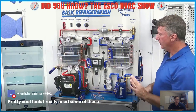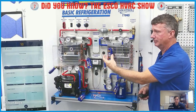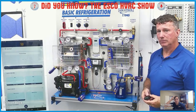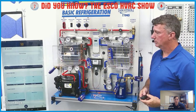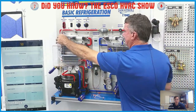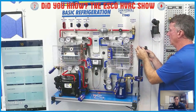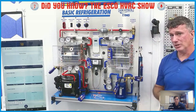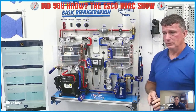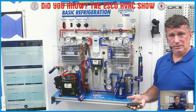Okay. So another item that you sent for us to be able to experiment with is? Yeah, the mano or the manometer, right? So we're taking our static pressures of the system or looking for total static or pressure drop across specific components, whether it be coils or filters or the whole system. So I'm actually going to do the same with it. I'm going to bring it around so that we're going to be measuring pressure now on our airflow as well, so that we'll be measuring across the evaporator. Okay. Is that it?